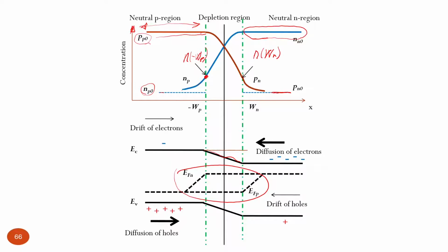You can get some effective concentration of charge carriers which are at a given moment inside the depletion region of the p-n junction, but that does not correspond to a real equilibrium condition, because you need to inject them always in order to extract, so to get some equilibrium concentration. But that is usually not considered very much in a p-n junction specifically.